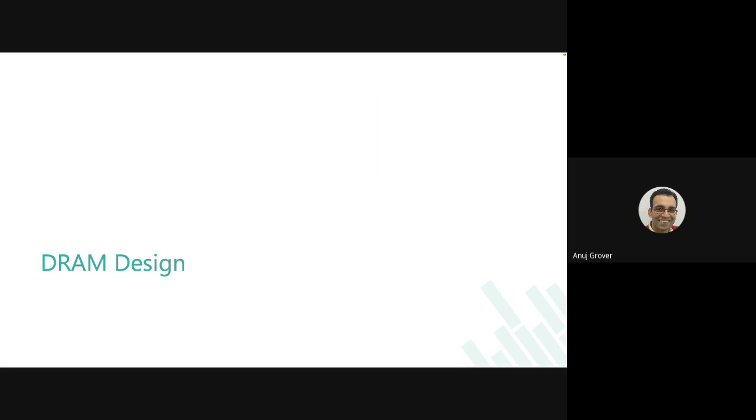It's not shown in the 6T memory cell, but it is also some charge storage mechanism. You're storing some charge on Q and Q bar, whichever name you want to put. So if you're storing some charge, there is bound to be some capacitor. DRAMs also store some charge on a capacitor only, but this capacitor is a floating capacitor.